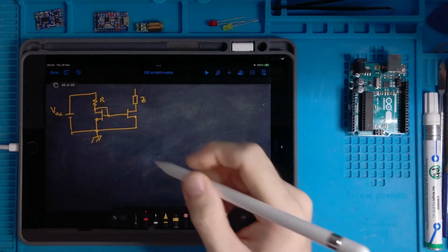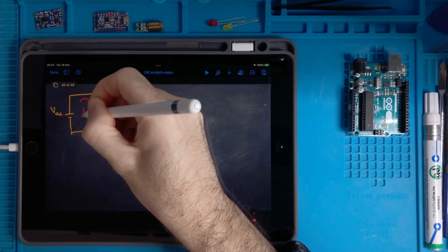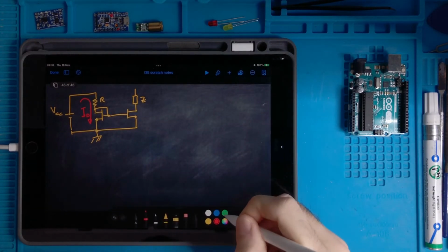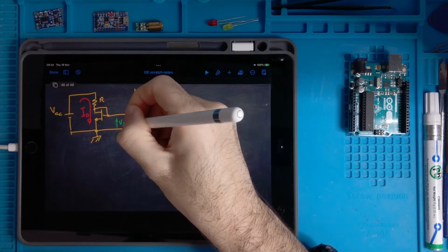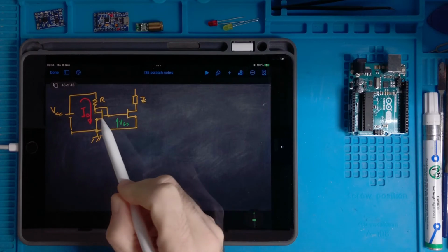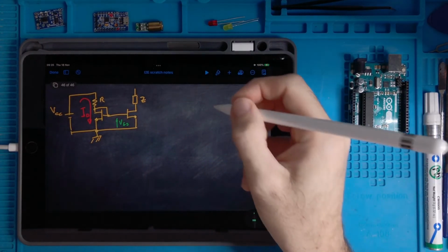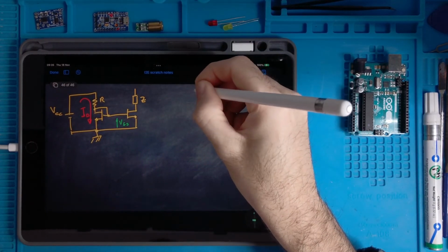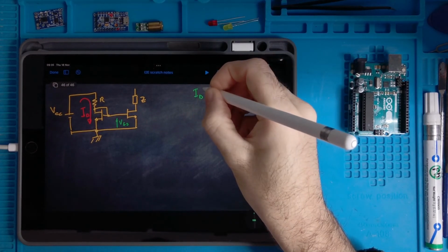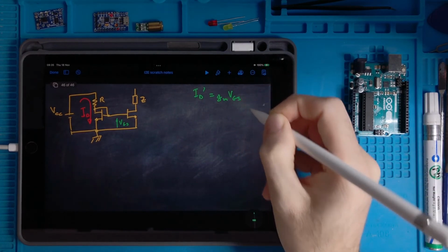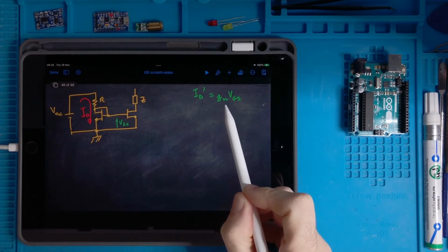So the circuit on the left makes a certain current ID flow in this thing, and this corresponds to a certain VGS here. But now I connected another transistor equal to this one, which means with the same Gm, and so for this transistor, the one on the right, this relation ID, let's call it ID prime, equals Gm VGS still holds because it's the same type of transistor.